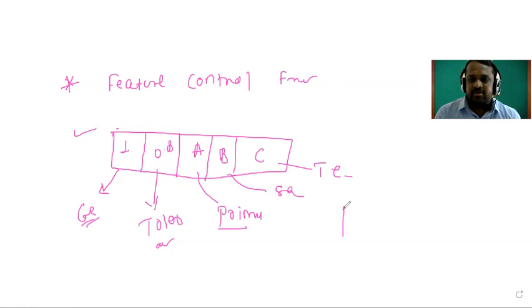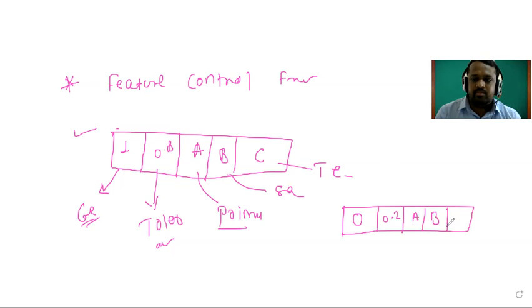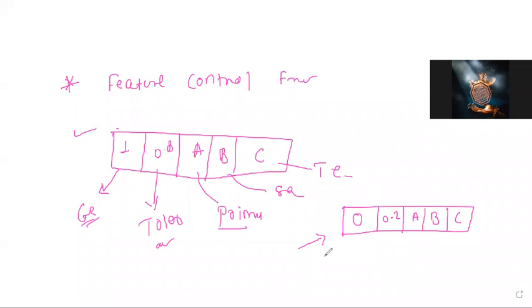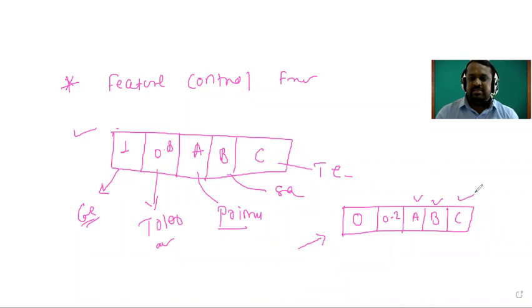If they have given it like this, tell me how we can read it. Circularity of the shaft should be within a tolerance zone of 0.2 mm, with respect to datum A, B, C. This is called the feature control frame.